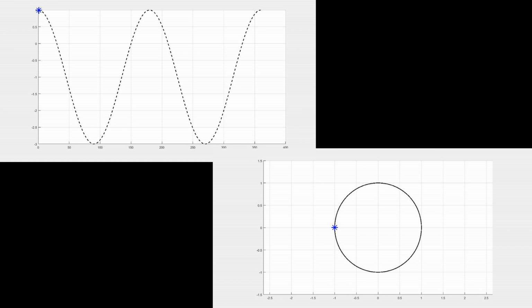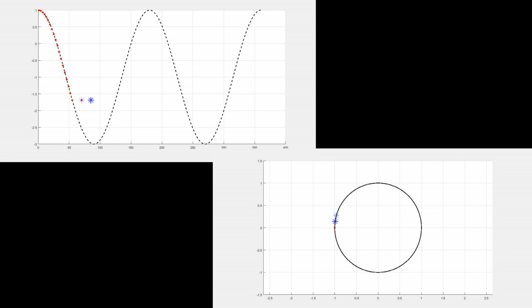Mapping the cross-section of a cylinder onto Cartesian coordinates yields a sinusoidal wave. In a perfect flow without separation, a Cartesian plot of pressure around the cylinder should be a perfect sinusoidal wave as well. However, fluctuations arise due to viscous effects along the surface of the cylinder, the most drastic of which being separation. When separation occurs, turbulence is introduced, which actually appears to be somewhat constant to the pressure ports due to the chaotic and multidirectional properties of turbulence. This means that the pressure plot around the cylinder will detach from the sinusoidal wave, remain constant throughout the wake region, and then rejoin the sinusoidal wave at the location of separation on the bottom surface.